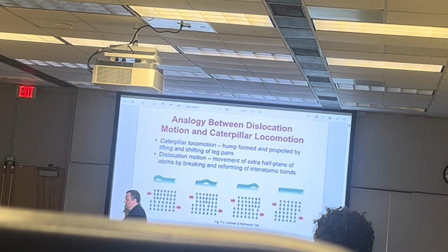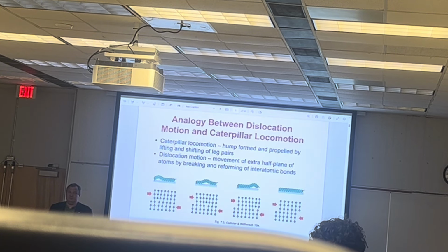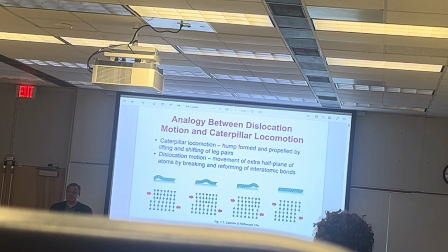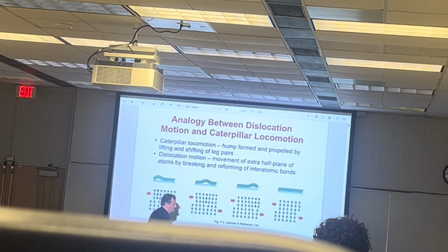It is doing certain things at a small scale and a small distance, because otherwise the energy to do that would be very large. And this is the mechanism to minimize the energy for the process of plastic deformation. Believe it or not, the first dislocations, I think they're called Somigliana and Volterra dislocations, were predicted by mathematicians.